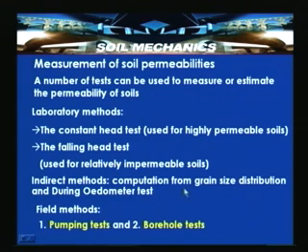Indirect methods are computation from the grain size distribution and the oedometer test. In the field methods, we have introduced two methods: pumping methods and borehole methods. Particularly, the Packer's tests are very famous. Here we are not discussing the field methods, but there are field methods available based on pumping tests for an unconfined layer or a confined layer under an impermeable layer or under a permeable layer. So, Packer's tests are very famous in determining the permeability value in the field.